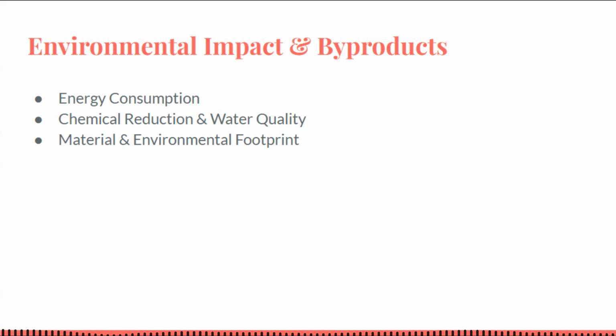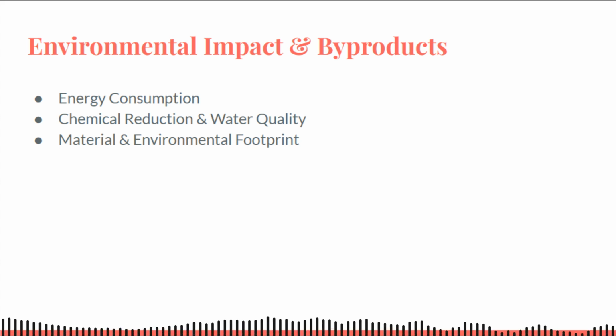Even so, the cost in electricity is modest, perhaps a few dollars per month, relative to the benefit of reduced chemical usage. Some advanced systems further optimize energy by only activating the ozone arc when needed. For example, some units sense ORP or have cycles. The UV in an AOP stays on during operation, but UVC lamps are generally efficient and low heat.